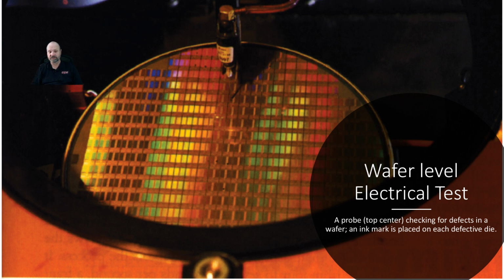Now, of course, they don't use ink anymore. They track wafer maps, and they know exactly which chips have passed and which haven't. So when they dice the wafers up, they cut them up, they know which ones to package and which ones not to. An important note is that if I were to package all the chips, the good and the bad ones, and then test them, it would cost twice as much to throw out a chip.